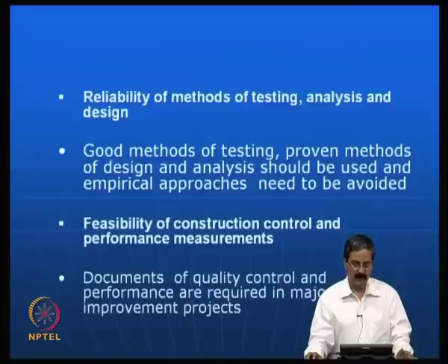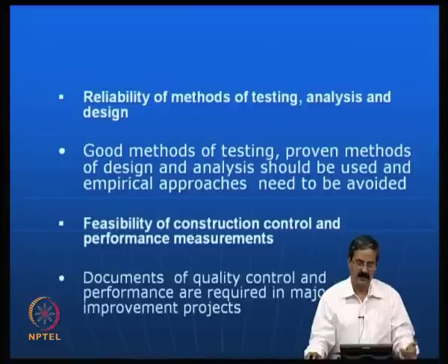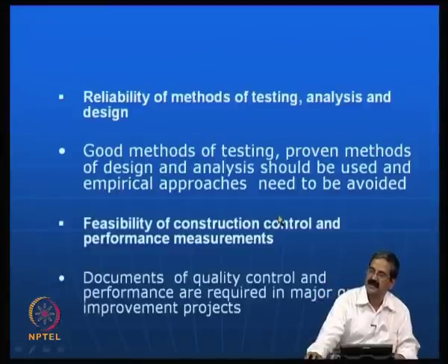And another important point is the reliability of methods of testing. Why it is important is that if the testing is correct and analysis is correct, you can come out with a proper choice. Even the choice of ground improvement techniques depends on this, because I have seen a case wherein the grain size distribution itself can be misleading. Based on grain size distributions, there is a very thin margin in choosing these materials. The efficiency of the technique depends on many properties of the soils that need to be improved. So, one should do proper testing.